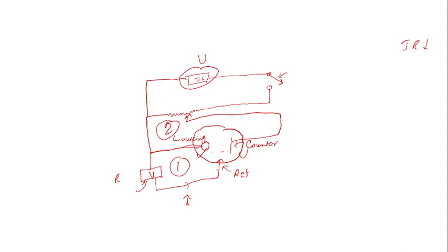In the first assembly what we are doing, we are adding one reference electrode, and here we are providing a voltmeter. This V is representing voltmeter, which has very high resistance. Because it has very high resistance, a very minute amount of I will be flowing. Because I is very less, IR drop will be very less, and you can maintain a constant potential here.